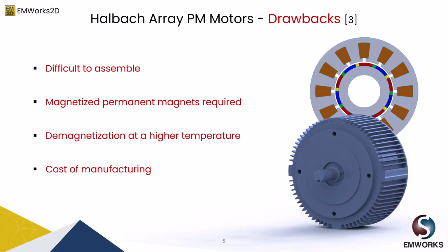Last, we have the cost of manufacturing. Since, as we discussed, it is very difficult to assemble, and we need very high strength glue to combat these forces during the assembly process, its cost of manufacturing is basically higher compared to radial flux PM motors.